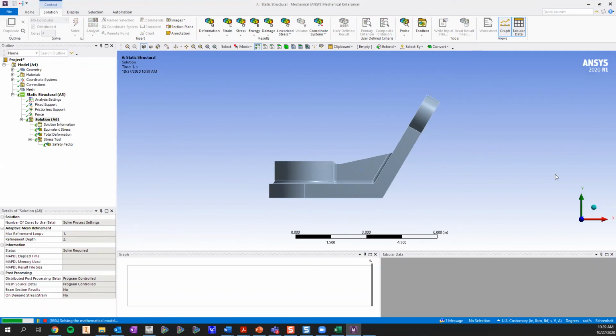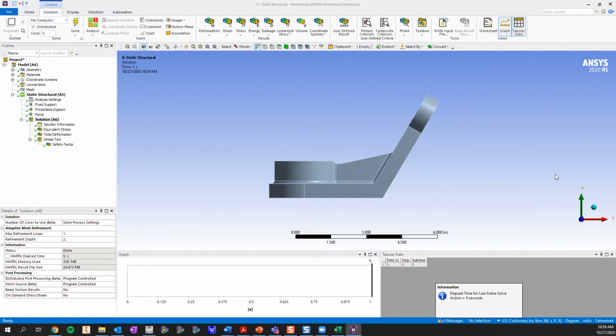So rather than setting up various different geometries in my CAD or even doing it in SpaceClaim and doing different studies and duplicating different schematic studies and solving this over and over and over again, I just used DesignXplorer. It took me approximately 30 minutes and I set a lower and upper bound of ranges that I wanted it to study in.